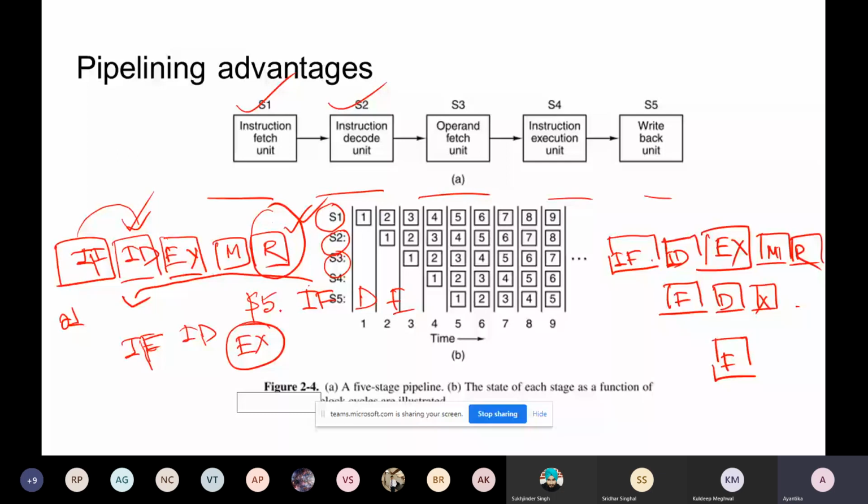But in this stage, register 5 is still not updated with your previous computation, because it has not yet reached the register write back stage. So the data you are using in the second instruction is some earlier data or junk data.